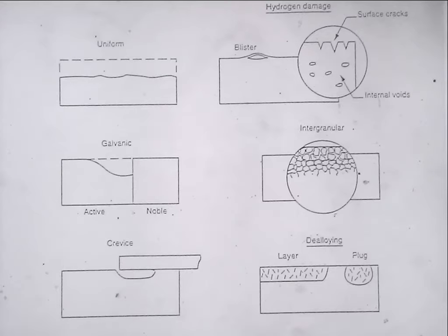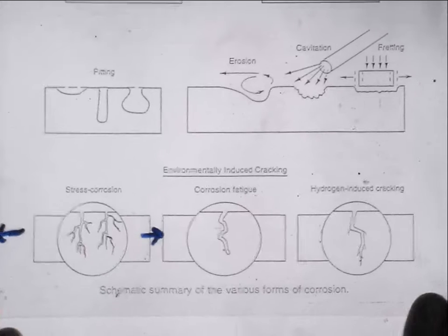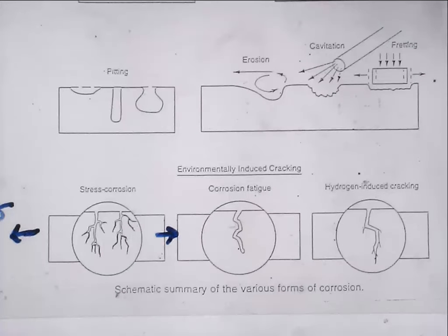Okay, good afternoon everybody. Sorry, it's a slightly late start. If you remember, we were talking about different modes of localized corrosion, and we had just started to look very briefly at the combination of corrosion and stress. And there are three formats of that. Stress corrosion cracking, which we're going to talk about first, which has a static load applied at right angles to the crack growth direction.